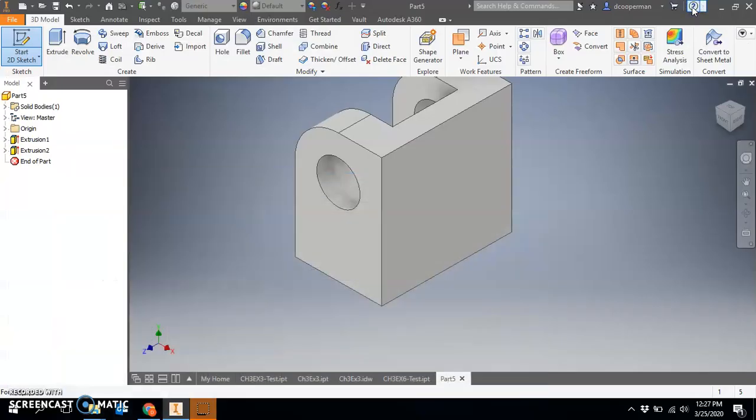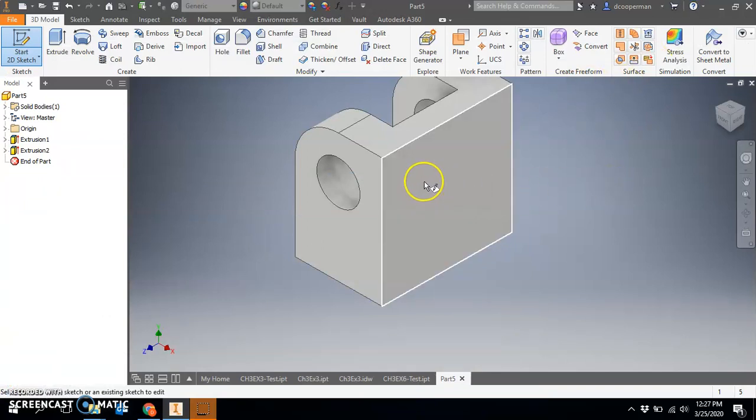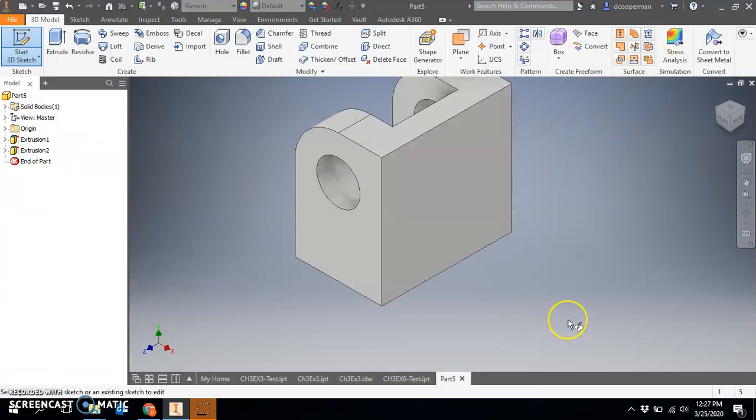So how does that help us? How could we draw that? I mean, if I extruded this larger square in that direction, that's going to be a solid trajectory. I need a piece that transitions from a 6 by 6 square down to a 2 by 2 square. We actually can't draw this with the features we know up until this point.